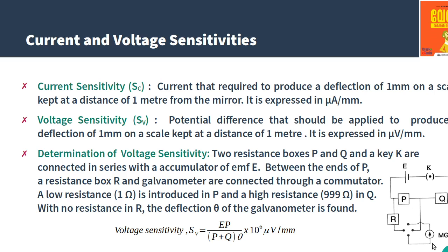Here we fixed the galvanometer, and there we found the current sensitivity K, and from that the maximum current Ig that can be passed through the galvanometer, and we also measured G. From that we calculated the value of S, the small shunt resistance needed to convert the galvanometer into an ammeter. The same arrangement we are using here.